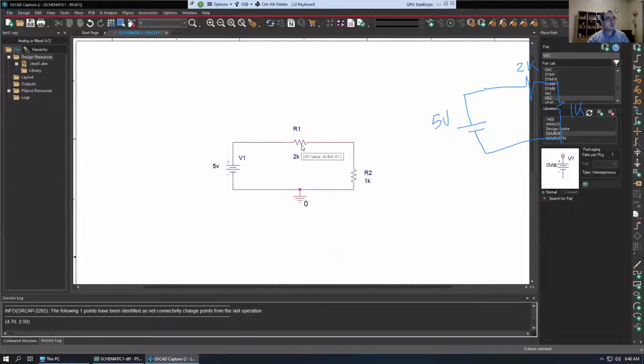All right, make sure your wires are not loose. For example, if I drag this resistor up and down, I see that it's connected to the circuit. Same thing here. If you drag this right and left, also make sure it's connected to the circuit so that you don't get an error when you run the simulation. Now let's see how we can run the simulation for this.